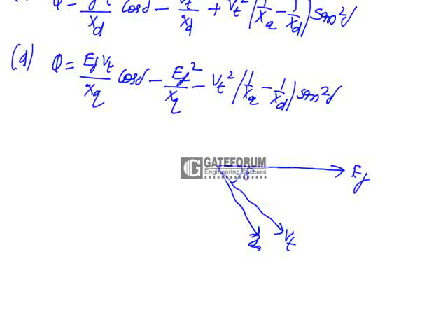Now here, this is at an angle phi. This armature current will have a direct axis current as well as a quadrature axis current. This one is the direct axis current, whereas this one is the quadrature axis current. The resultant is the armature current Ia. Now, what is the terminal voltage Vt? In series with Vt, we have a drop of Id into Xd.